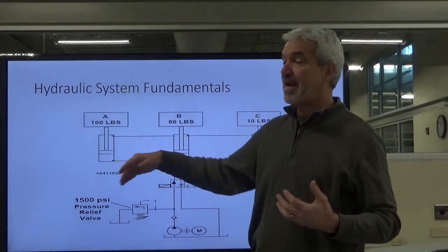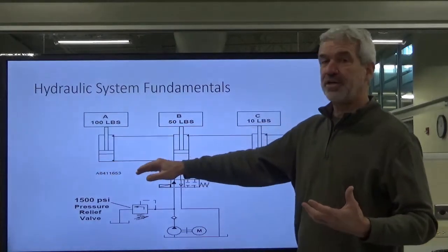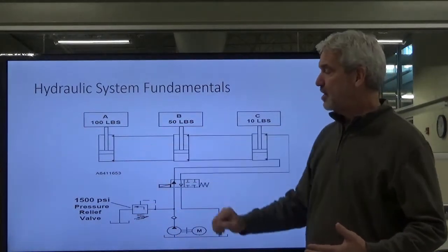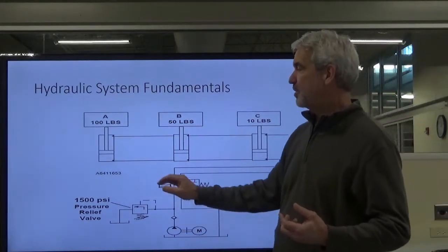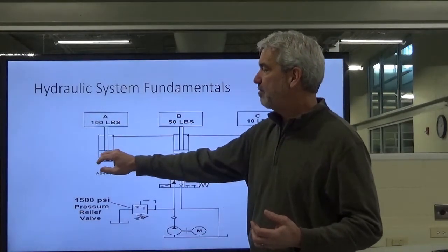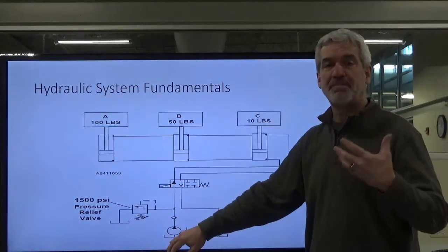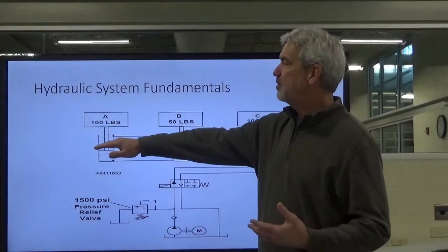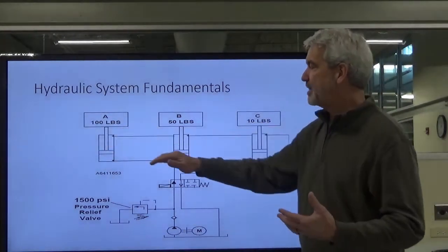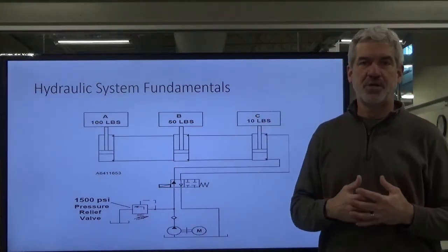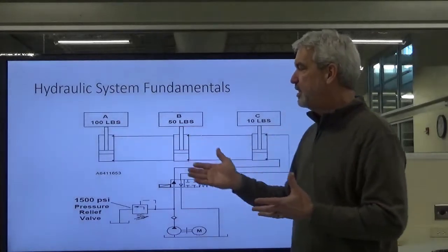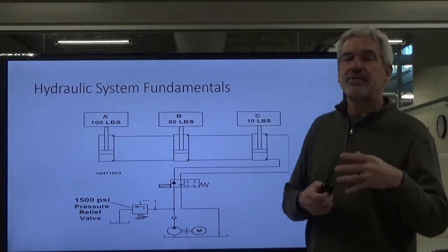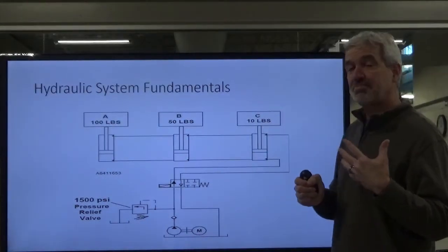And then finally, the path of least resistance is the last cylinder. It's got 100 pounds on it, and it will, provided that the pump is providing more than 100 pounds, let's say the pump puts out 500 pounds of pressure, okay, as long as we can get flow in there and create enough pressure that's greater than 100 pounds, and our pump pumping 500 naturally would be, we are going to be able to raise that, and then we will continue to raise it until all 3 of them are maxed out. We have no more flow, okay, we have nowhere else for the oil to flow. So we have maxed out on our flow. We're going to get to what that means to us as far as pressure in just a little bit.